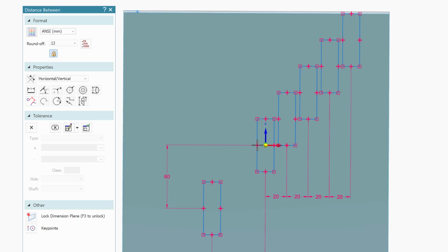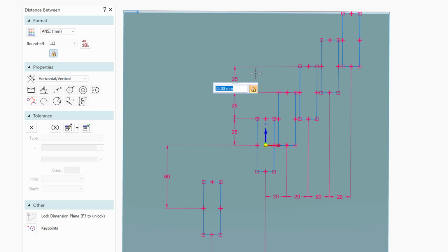From the center here to the new location here, this should be 25, and to the other center here is going to be another 25, and to the center here is another 25, and to the center here the other 25. So I succeeded in making a series of them every 20 in the X direction and 25 in the other direction, and this is how you make the copy. Make sure the copy is highlighted, meaning you don't move it, you move a copy of it.